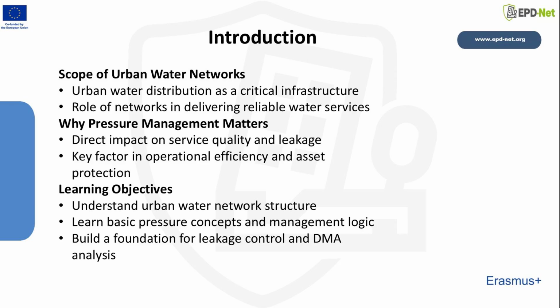Pressure management plays a central role in water distribution systems. Pressure levels directly affect service quality, system reliability, and the occurrence of water losses. Inadequate pressure can lead to service interruptions, while excessive pressure increases leakage rates and accelerates infrastructure deterioration.